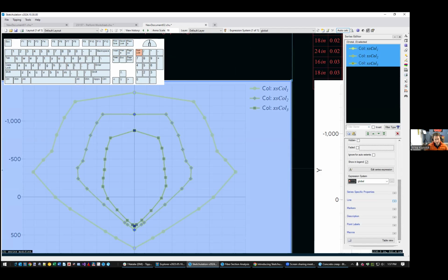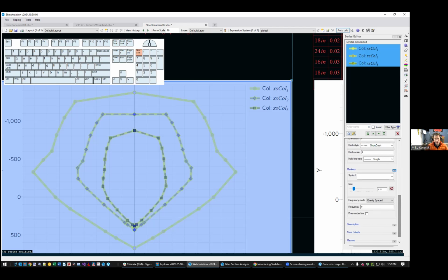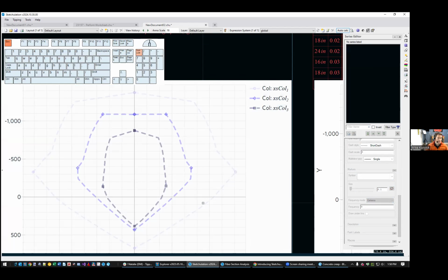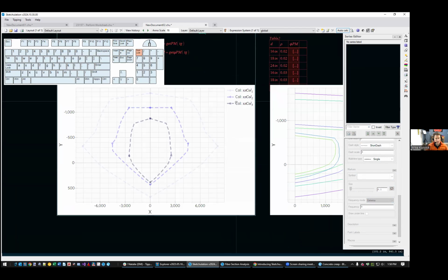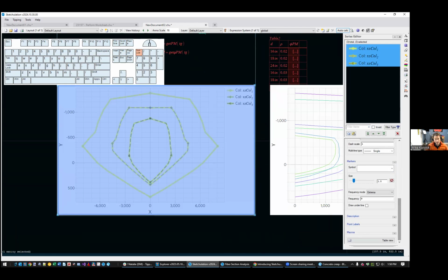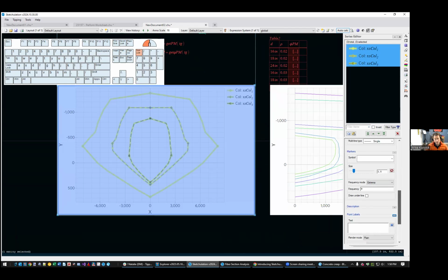Various other features. What I wanted to just show here is that you can change the thickness of the line. Here, different dash styles are available in the drop down there. There you have the markers, so you can select different markers, change the marker size. You can tell it whether you want the markers evenly spaced or maybe just in particular places. Maybe you want them at the extrema, so they do mark the series, but not on every single point, so it's not dominating. And then one thing I really wanted to touch on here was the point labels.